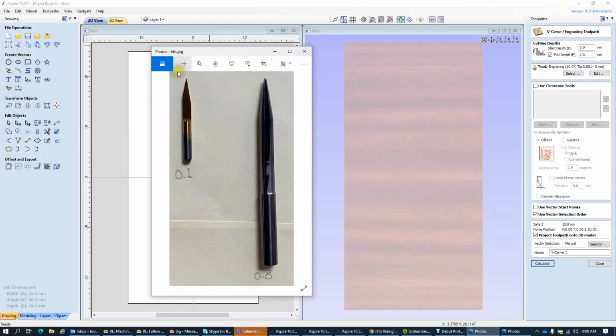All right. So anyway, if you just look at the top really close, you can see this has a little bitty flat, and this has sort of a ball end on the end of it. These bits that you have that look like this with the gold on the top have a 0.1 millimeter flat. So that's how flat the top is of that bit right there. It's 0.1 millimeters. So 0.1 millimeters is roughly 3/1000ths of an inch. Let me just calculate that.